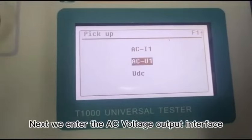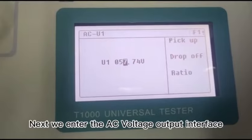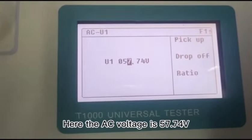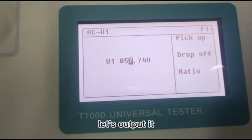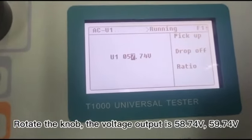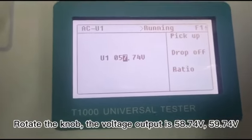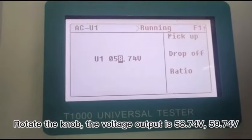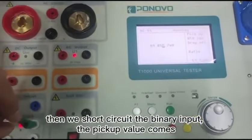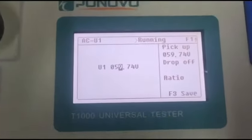Next we enter the AC voltage output interface. Here the AC voltage is 57.74 volts. Let's output it. Rotate the knob, the voltage output is 58.74 volts, 59.74 volts. Then we short circuit the binary input, the pickup value comes.